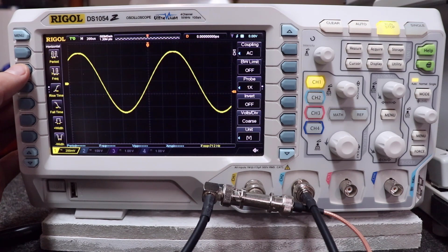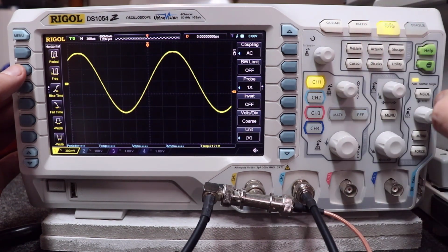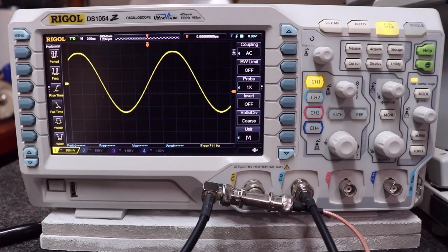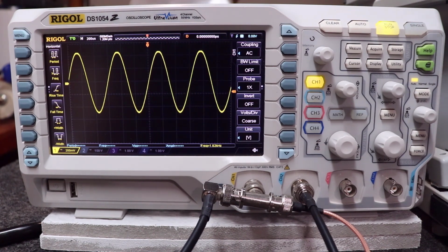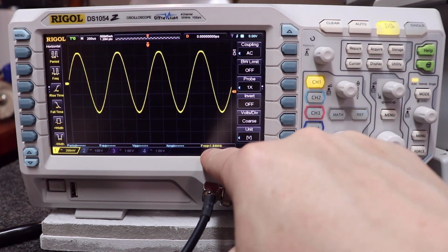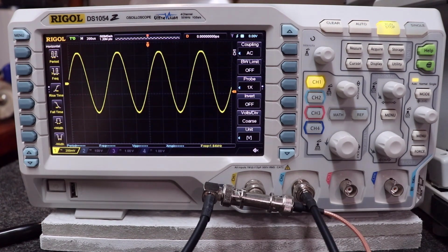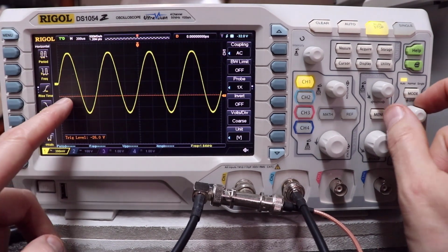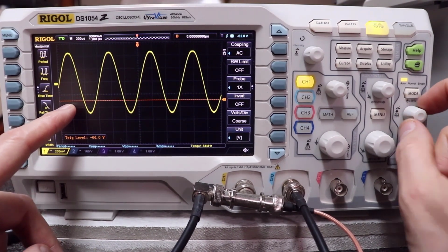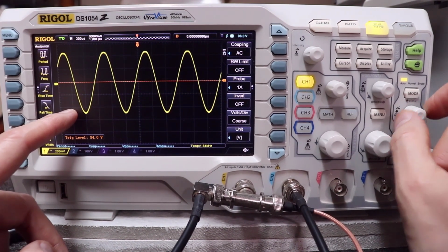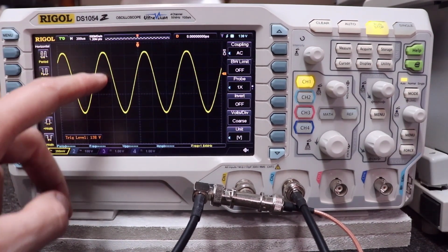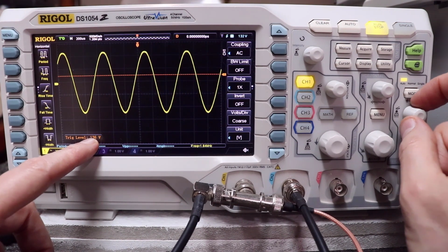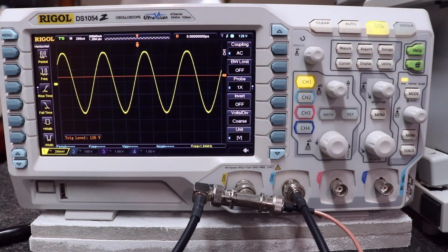Like right here, I can click frequency on channel 1 here. And all of a sudden right here, I'm measuring. This is a 712. Look at this. As I change the frequency, instantly this thing is measuring the frequency over here on the left and displaying that for me. Over here on the right, you've got trigger. Look at this. Remember before I would adjust the trigger and I didn't see a line. Here, it lets me see a line, exactly what I'm triggering on. So if I had something that alternated every other time and it was smaller the second time around, I can make sure I'm far enough down and it'll tell you the voltage level that it's actually triggering on here.